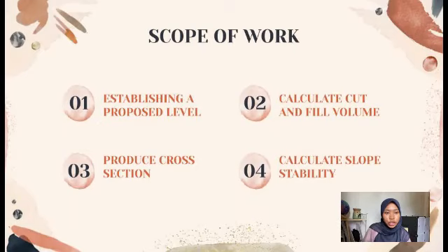To summarize the job scope of the Earthwork Department, we are in charge of work regarding the earth, and this work is as follows. Number 1, establishing a proposed level. Number 2, calculate cut and fill volume. Number 3, produce cross-section. And number 4, calculate the slope stability.